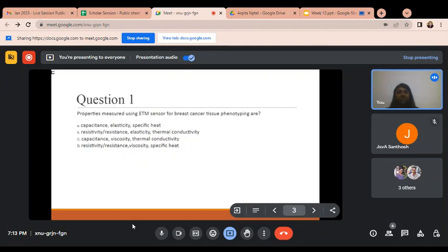So by this process we remove the organic contamination which is present in the wafer. And the second process is the RCA2, which is standard cleaning process 2. Why is it required? If inorganic or metal particles are present on the wafer surface, we remove this type of contamination by using the RCA2 solution. How to prepare this RCA2 solution? First we prepare a 6:1:1 ratio of HCl, H2O2 and DI water.